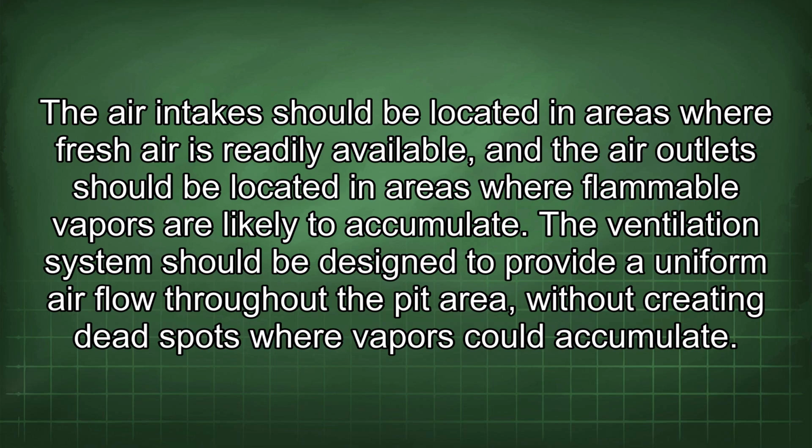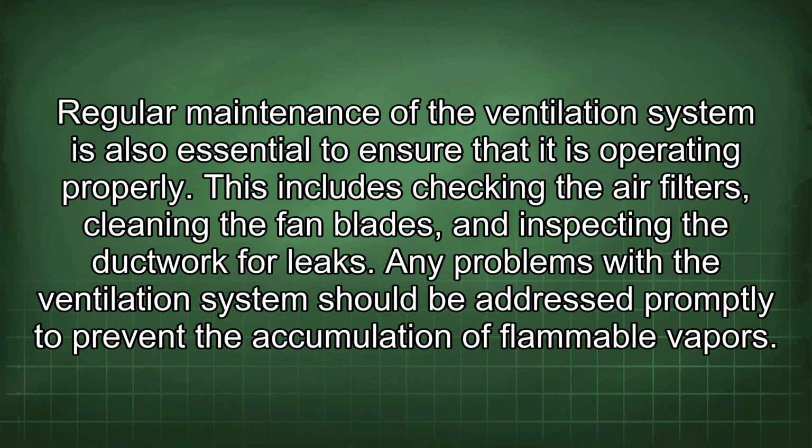The ventilation system should be designed to provide a uniform airflow throughout the pit area without creating dead spots where vapors could accumulate. Regular maintenance of the ventilation system is also essential to ensure that it is operating properly. This includes checking the air filters, cleaning the fan blades, and inspecting the ductwork for leaks. Any problems with the ventilation system should be addressed promptly to prevent the accumulation of flammable vapors.